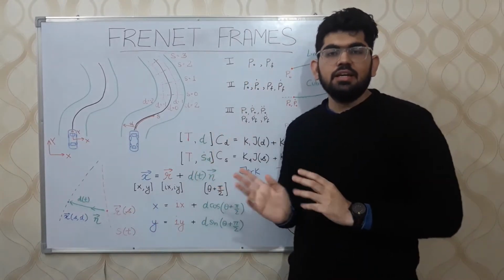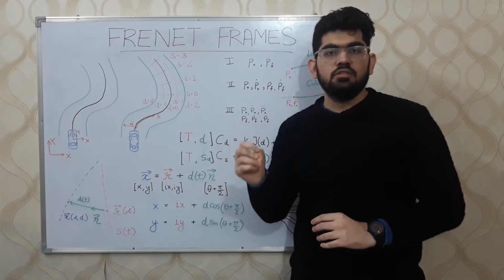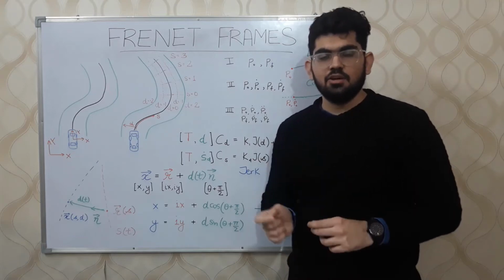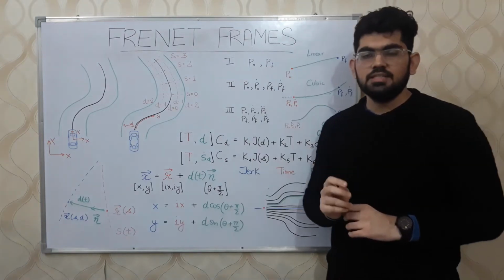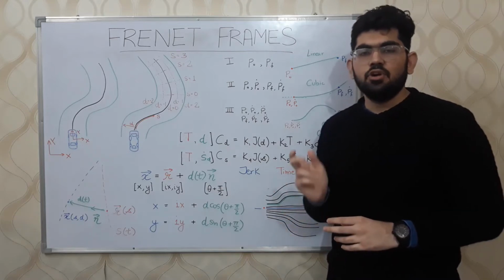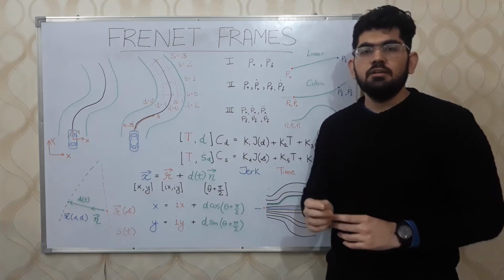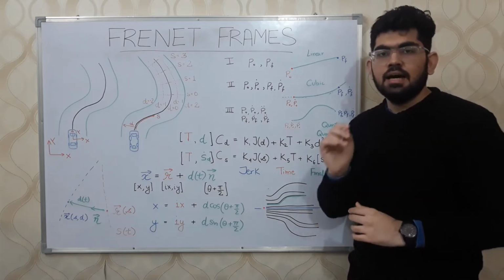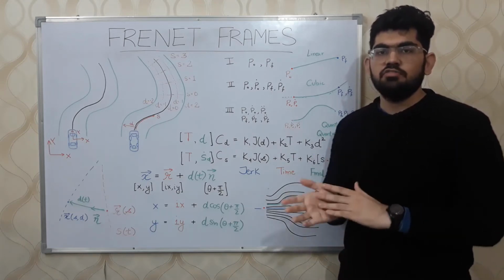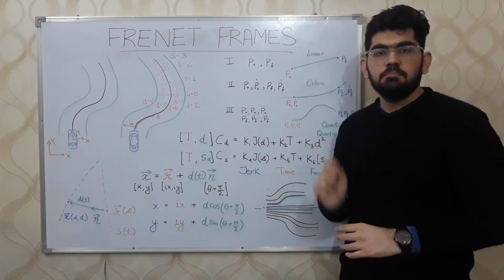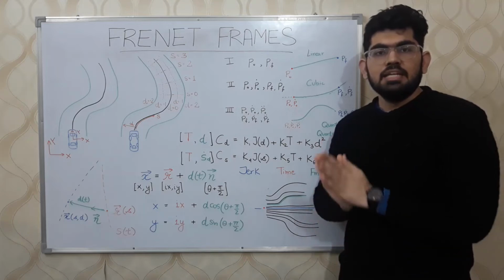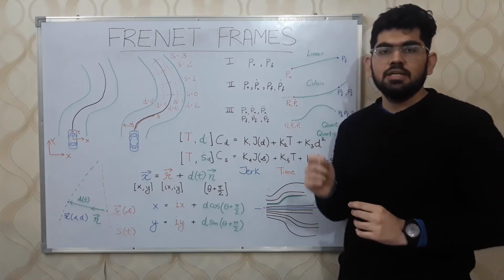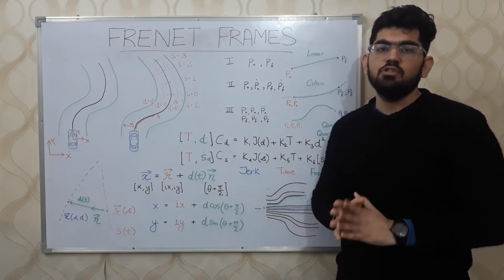The Frenet frames over here help us describe the path that the robot needs to generate and as well needs to follow. The actual path actually consists of polynomials. The whole process works something like this. In the S and D coordinate frames, we derive a number of different polynomial paths, like we can see over here. These polynomial paths are generated by varying certain initial or final conditions. From these paths, the path that avoids the obstacles and minimizes a given cost function is chosen as the path to follow. Then the robot needs to give control commands to its motors to actually follow that path.